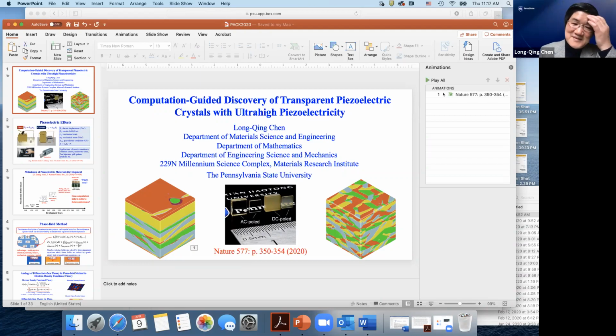Yeah. So I think also an indication, already with the very first data which were published, that it was a bit strange is that you see a lower loss tangent for the AC poled materials compared to the DC ones, and you would always somehow relate this loss in part to the domain wall density.